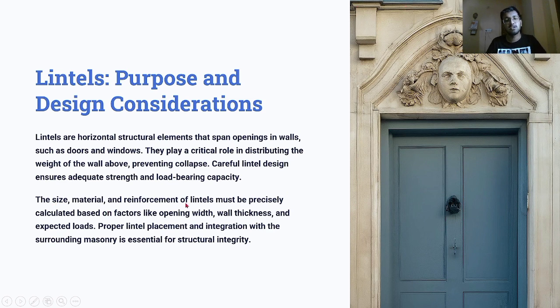The size, material, and reinforcement of lintels must be precisely calculated based on factors like opening width, wall thickness, and expected loads. Proper lintel placement and integration with the surrounding masonry is essential for structural integrity. So that's it with lintels.